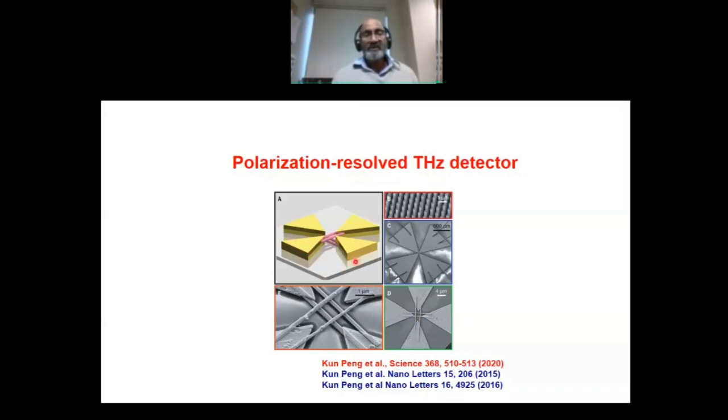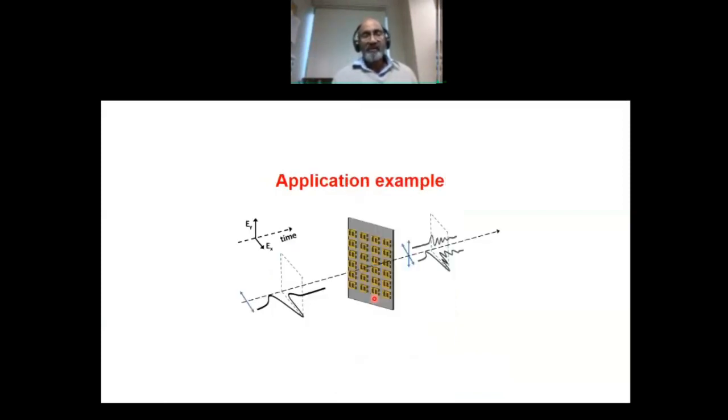You can see that in this case, she creates two sets of these bow tie antennas and tries to put the nanowires in orthogonal directions, 90 degrees to each other. You can see the close-up of this one. She was using two independent nanowires, one in one direction and another in the other direction. The challenge has been avoiding contact between the top nanowires and the bottom nanowires, and that's where she spent a lot of time optimizing the conditions in order to really do that. After 3 years, we were able to demonstrate excellent polarization-sensitive, phase and amplitude sensitive terahertz detectors.